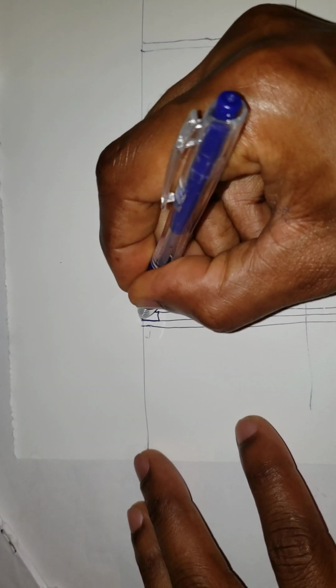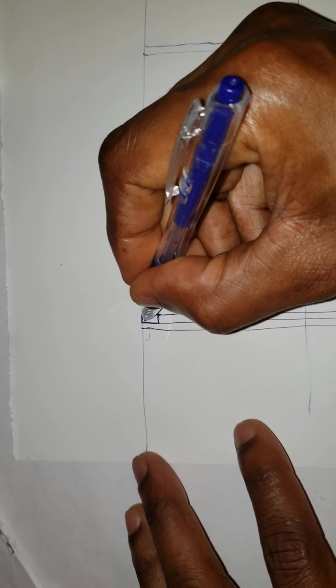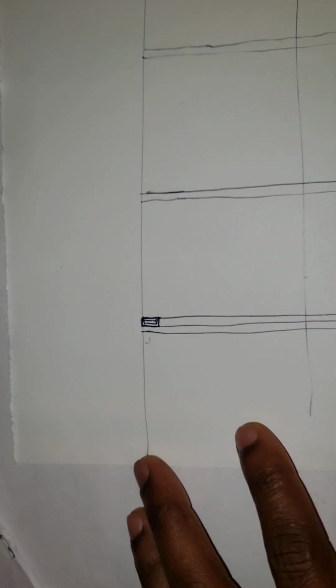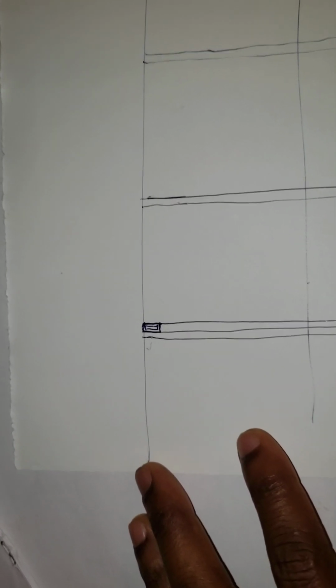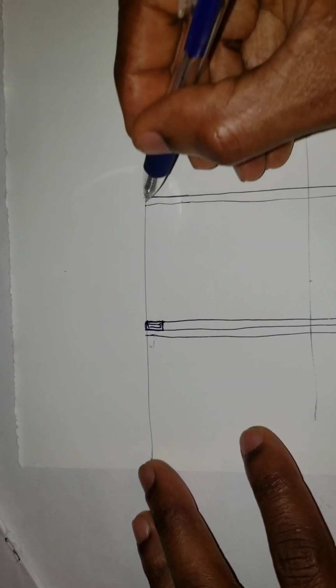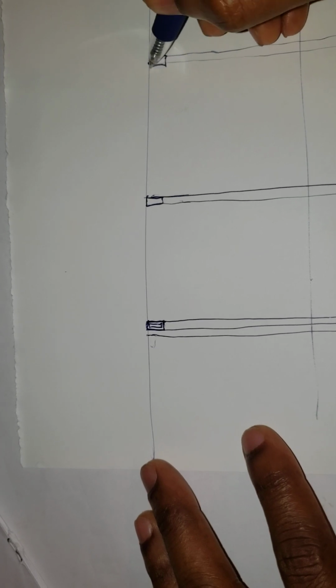Now, the next thing that we could start with is our ring beam. The ring beam is typically 150 by 300. We offset this. So in AutoCAD, I typically draw this at the outside of the drawing, and then copy and paste it into all these spots. So we have that across all of those.